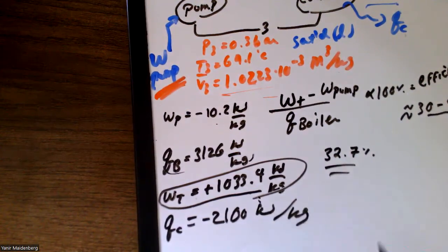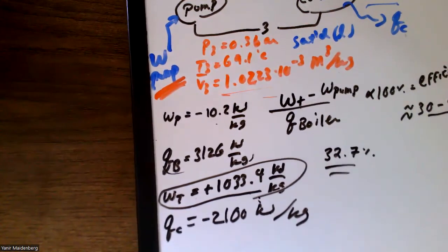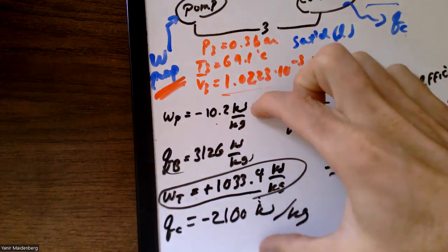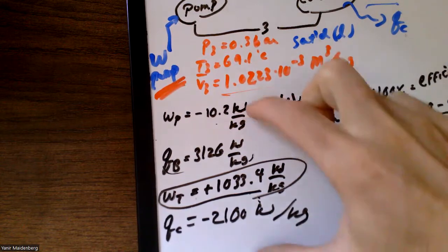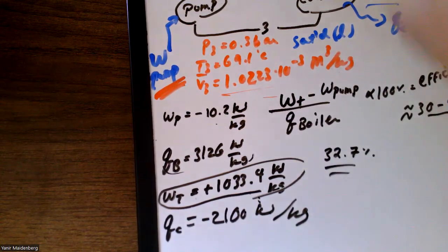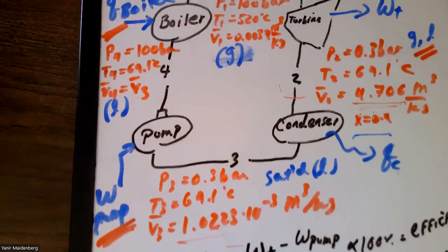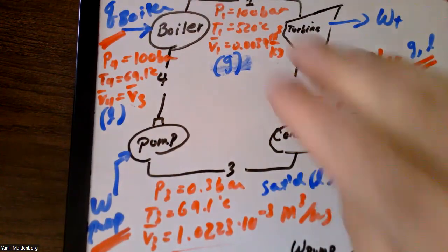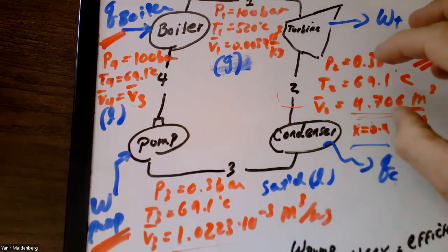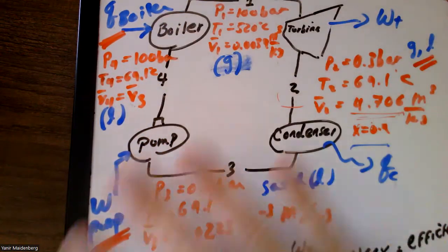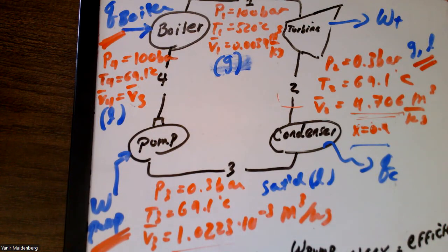I'm giving you all the numbers, so you can also figure this out now if you want to, but I'm just sketching this out. So again, you're going to determine these four numbers. You're going to calculate the efficiency, and you can try to sketch out what the states are. Usually that's your first step, like in any thermal question: state the states. And after you state the states, you can do first law and then eventually also second law analysis, and you can get the work and the heat and the efficiency, etc.